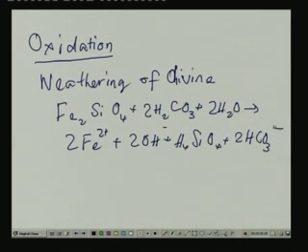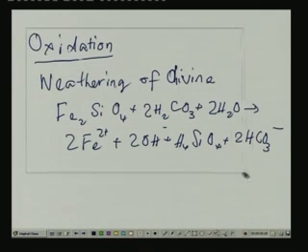Ion exchange. The illite mineral converts to montmorillonite, and this transformation originates from loss of potassium and uptake of magnesium. And then chelation. Chelation is essentially taking of mineral ions in hydrocarbon chains. That is what is meant by chelation. And let's take an example of leaching, because leaching is a very important weathering process in tropical and subtropical environments like those encountered in many parts of India.